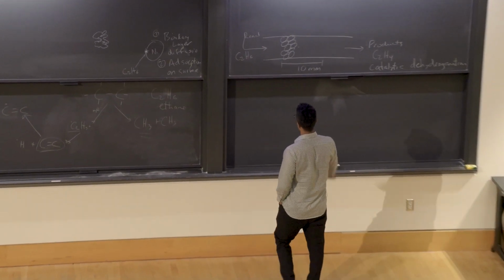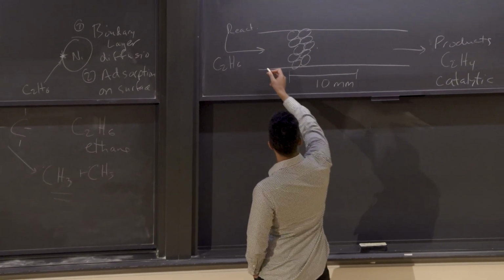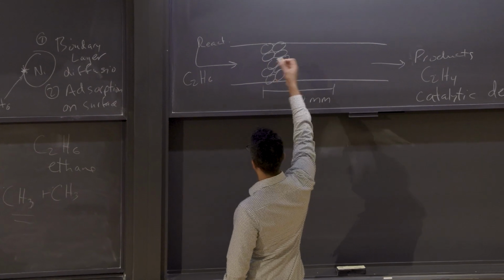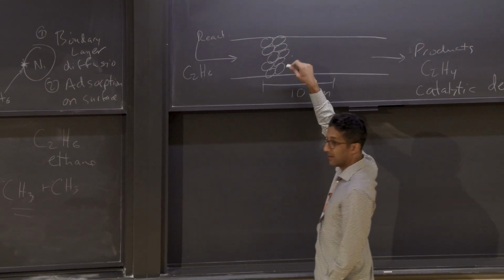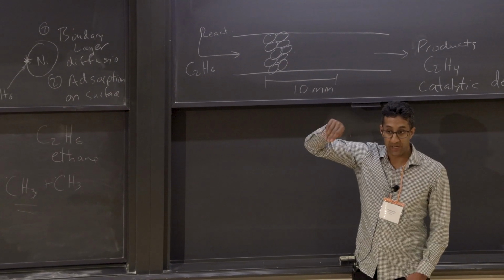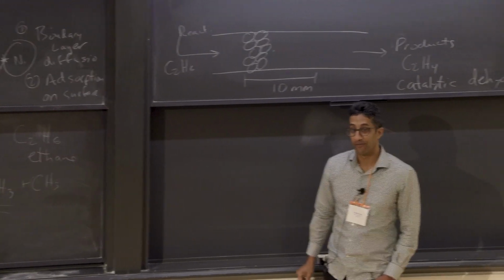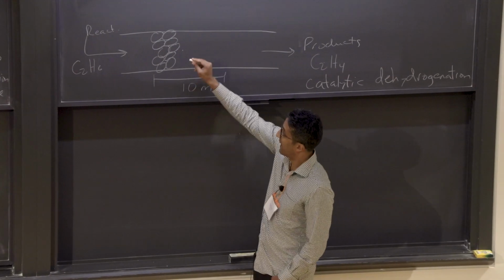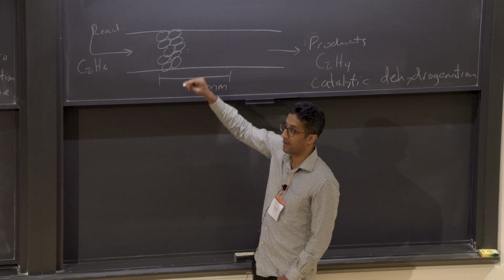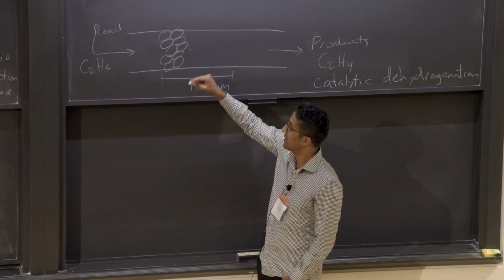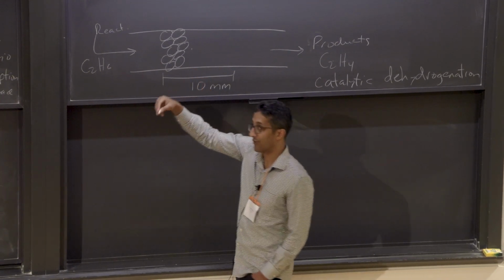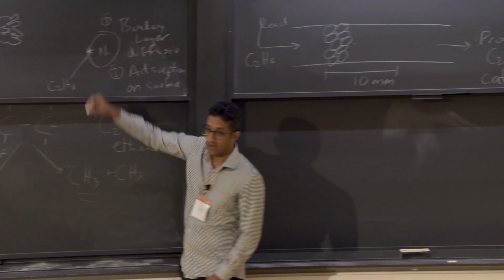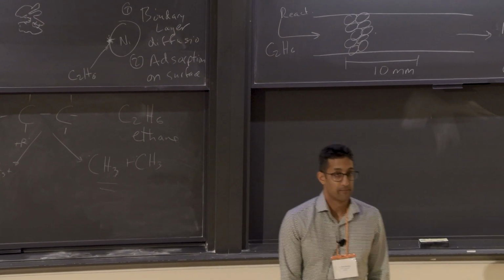We might know the boundary conditions coming into the reactor and leaving the reactor, we might know the overall flow is good, but again, where the kinetics are happening, the transport processes there are actually very complicated, yeah? And if you have a packed bed reactor, it'll depend on the size of the particles, the flow rate, and even the nature of the structure of the catalyst, yeah?